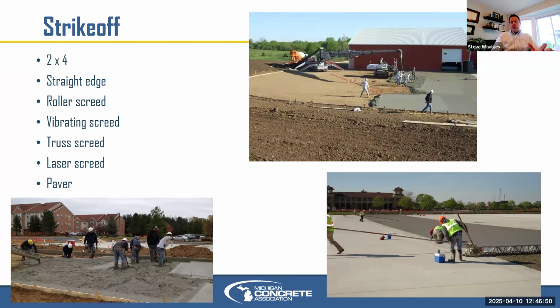Number one, as far as what material should we use? Do we use 22A, 23A, or should we go... MDOT uses a 4G drainable base. Personally, I like 21AA. It generally results in a material that's stable, but also drainable.